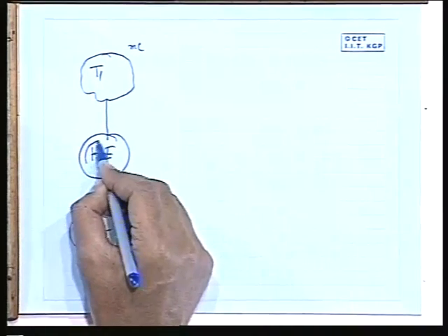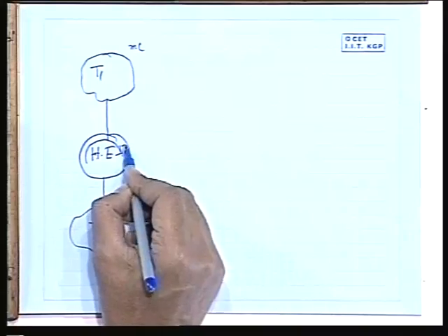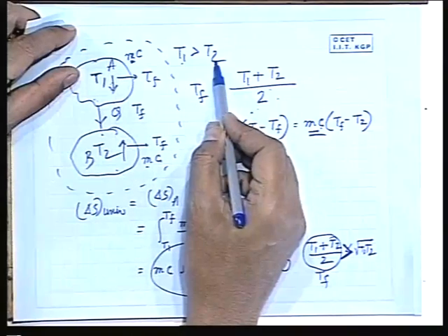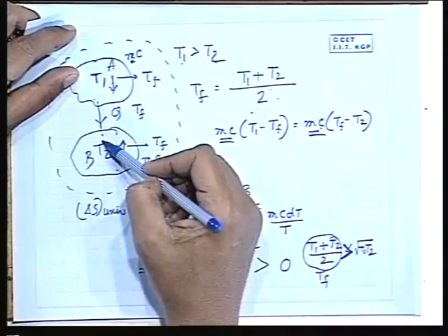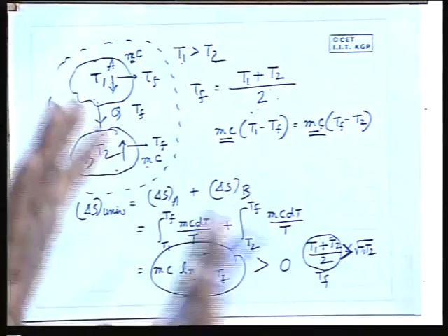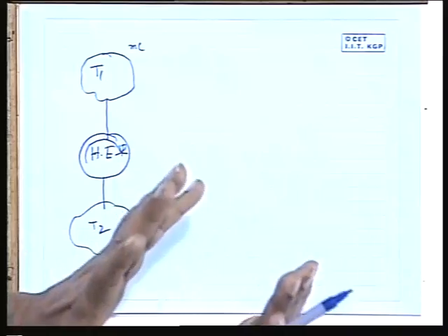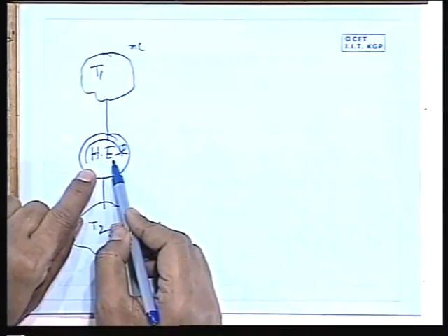And this heat engine is a reversible heat engine. So the concept is that two finite bodies at different temperatures, if connected by a diathermic wall, form an irreversible connection. That means the transport process, the heat transfer, will take place as an irreversible process. But these two bodies can exchange heat via some third body, not directly, in a reversible manner. That means they can be connected in a reversible manner via a third body, that is a reversible heat engine,